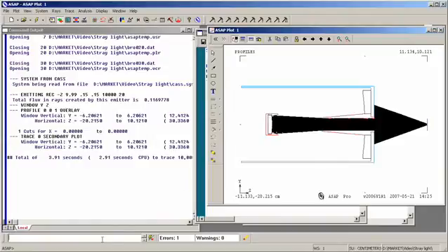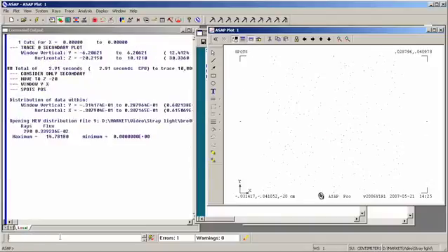We know from our previous ray trace of a point source that the image of the detector is at z equals minus 20, so we say consider only secondary, move to z minus 20, that is to say take those rays that are currently on the secondary mirror and move them backwards along their trajectories to the image plane z minus 20. We then set up a window and do a spot diagram.